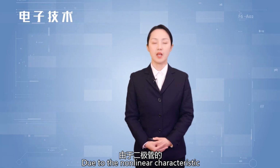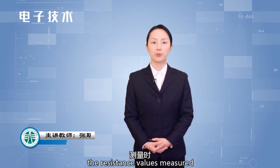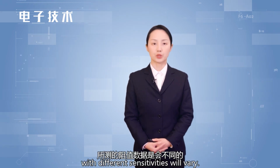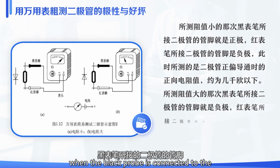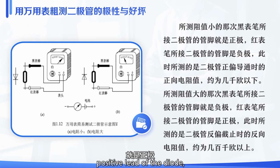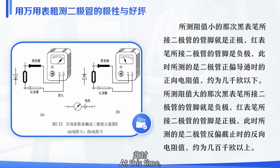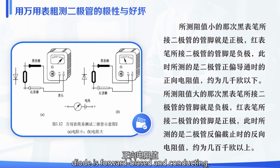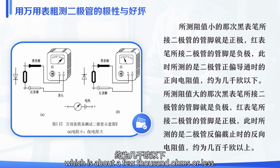Due to the nonlinear characteristic of the diode's volt-ampere characteristic, the resistance values measured with different ohm ranges or multimeters with different sensitivities will vary. The smaller resistance value measured is when the black probe is connected to the positive lead of the diode, and the red probe is connected to the negative lead. At this time, the measured value is the forward resistance when the diode is forward biased and conducting, which is about a few thousand ohms or less.